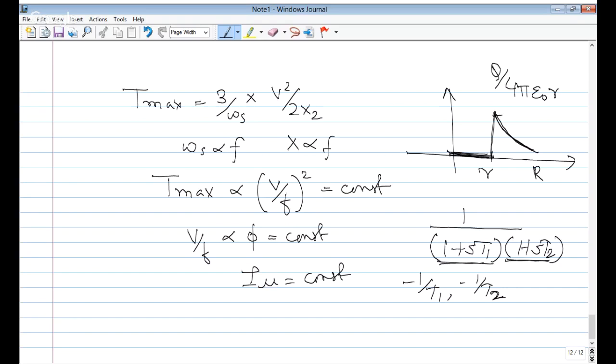So next is Naveen. Relays that are sensitive to power swings. Actually, Naveen, both the relays, impedance and reactance relay, are sensitive to power swing. Only mho relay is not sensitive to power swing. So the answer is both correct, A and B.